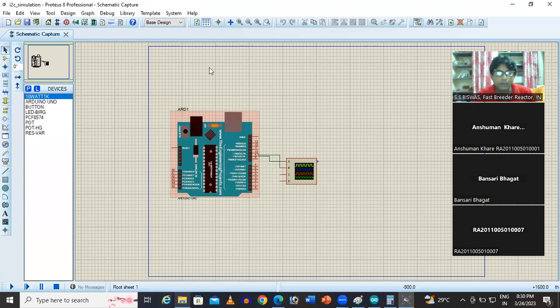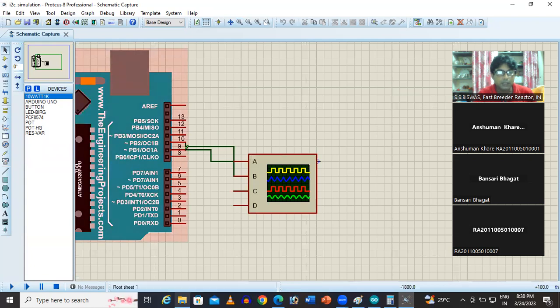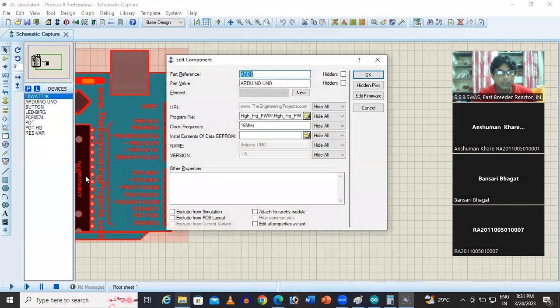And here, if I enlarge, you see, I have connected the CRO because of timer one. You can remember in the pin configuration, I defined PB1 and PB2 as output. And here, this is basically the output compare register channel A and channel B. There only these will connect. So one will give non-inverting PWM, another will give inverting PWM.